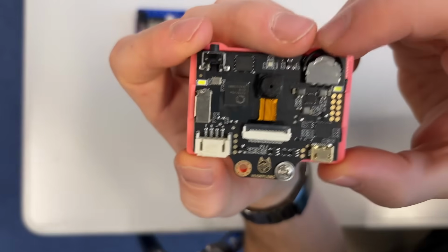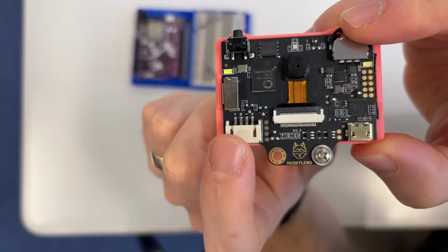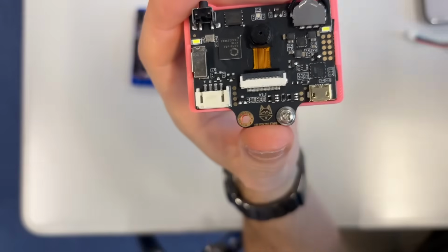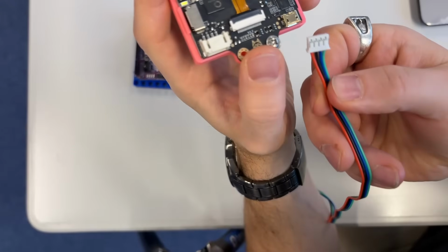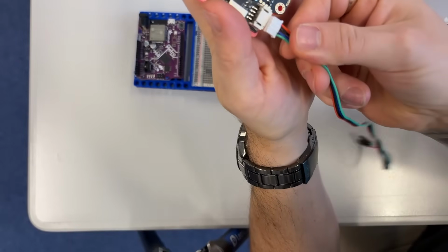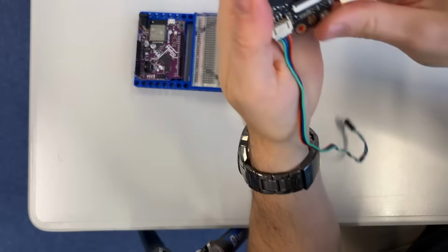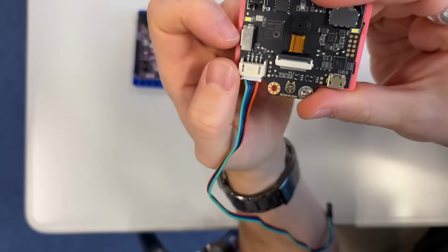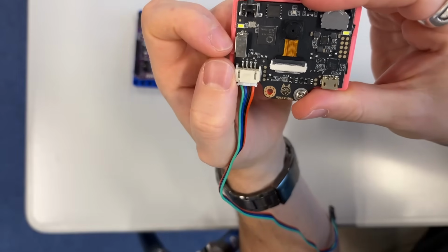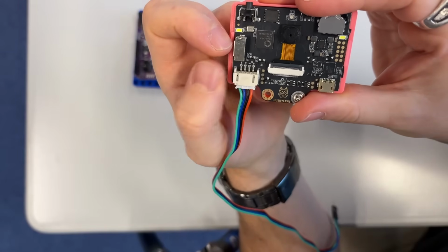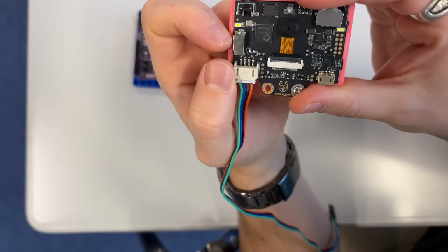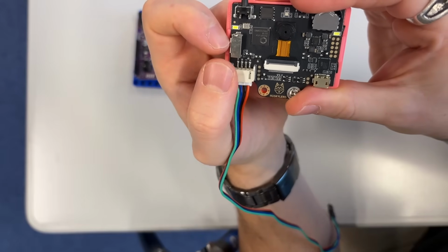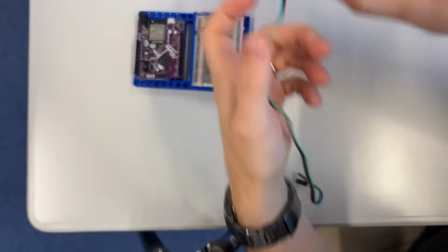And then we are going to be connecting down here to these ports. We have our T, our R, minus and plus for our power and ground. So I'm going to grab this HuskyLens connector here. We're going to go ahead and plug this in. And in our case, T is going to refer to green, R is going to be blue, and because we're going to use I2C for this tutorial, T actually ends up becoming your SDA or your data line. And blue, or R, ends up becoming your clock line.